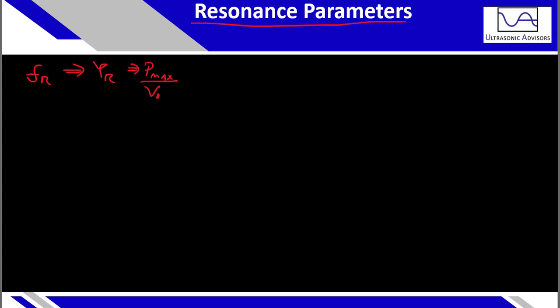So it's that ratio. If you're going from your impedance analyzer, it will likely be able to display real admittance or conductance, which are the same thing. But in order to calculate the value from impedance and phase, here's the formula for that.